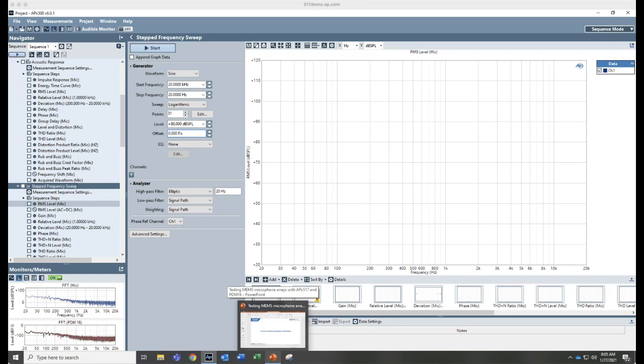This is a great question. The reference microphone that you are using is a pressure field microphone. If so, why not a free field one? Won't the measurements give you different results if you're using a free field, half-inch microphone, or a quarter-inch pressure field? So that's a very good observation. Let me explain a couple things. The first thing is that at a quarter-inch, and this is another reason why I like quarter-inch measurement microphones, a pressure field microphone and a free field microphone have the same frequency response in a free field.